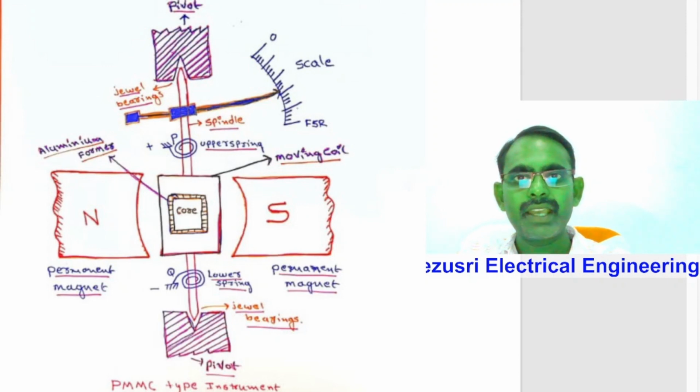Here, the pointer is carried by the spindle and moves over a graduated scale. The pointer is constructed with light weight. The section over the scale is twisted to form a fine blade to reduce parallax error in the reading of the scale. In many instruments, such errors may be reduced further by careful alignment of the pointer blade and its reflection in the mirror adjacent to the scale.